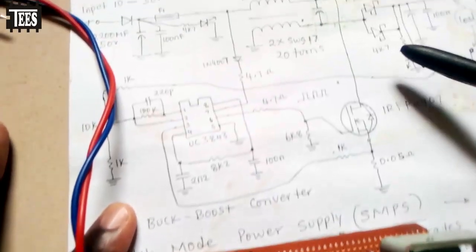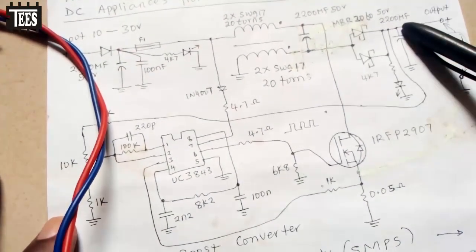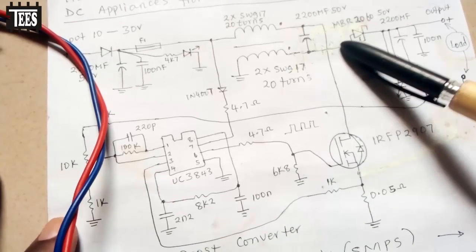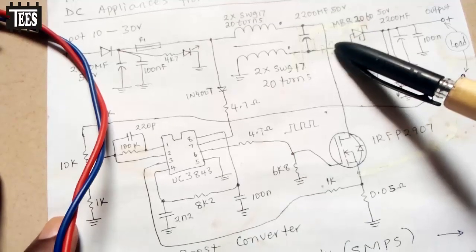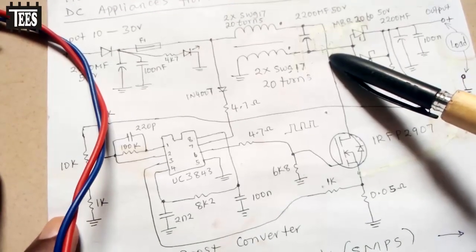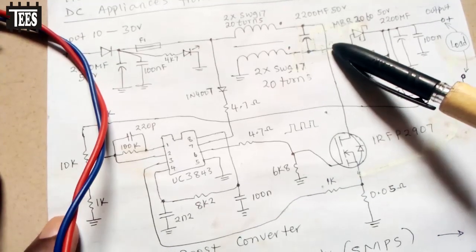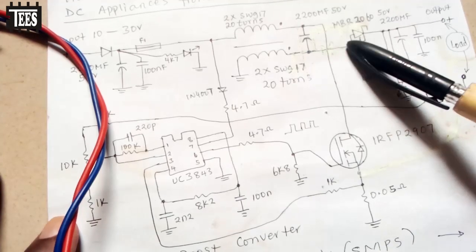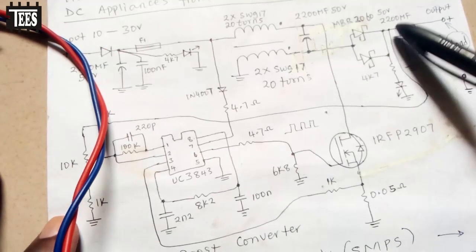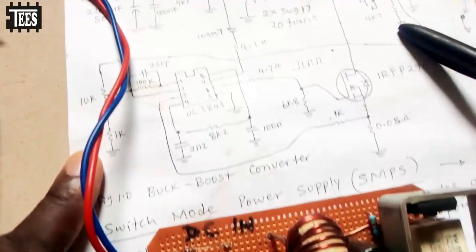Then after the diode, you need capacitors. It's just like if you are converting AC to DC. What you have here is just the behavior of alternating voltage, an oscillating DC voltage. So it is not a pure DC. That's why we need this high-speed diode, so that it will convert it back to pure DC. And then we have the filter capacitors that you are seeing at the output here. So that's how we get the pure DC out.